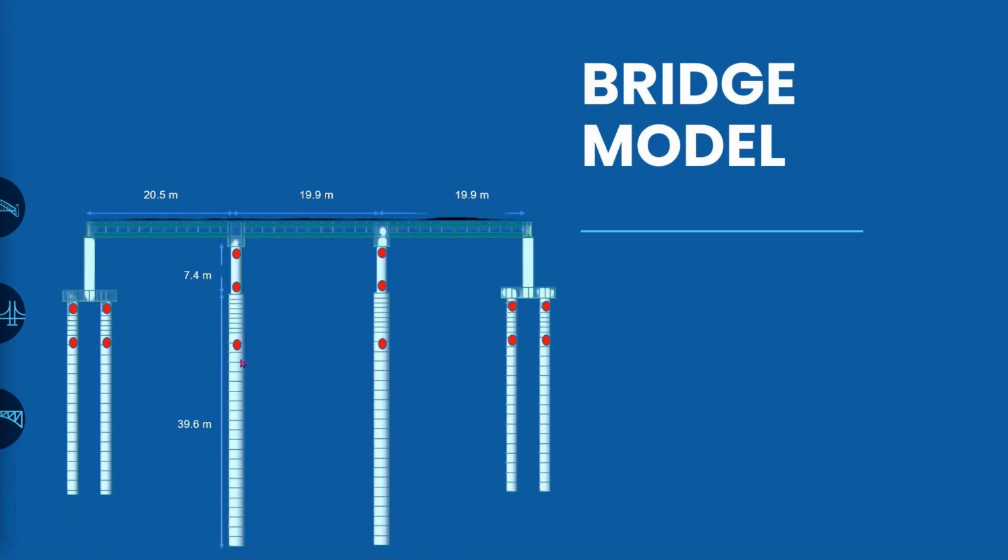Now, the other concern that we need to address is the expectations from the model that we are doing. It is very important that the plastic hinge in the structure shall form at the point where we are anticipating it to be. We do not want a plastic hinge to form within the piles. The reason being that the inspection and the repair of plastic hinges, if formed within the pile, is very, very difficult.